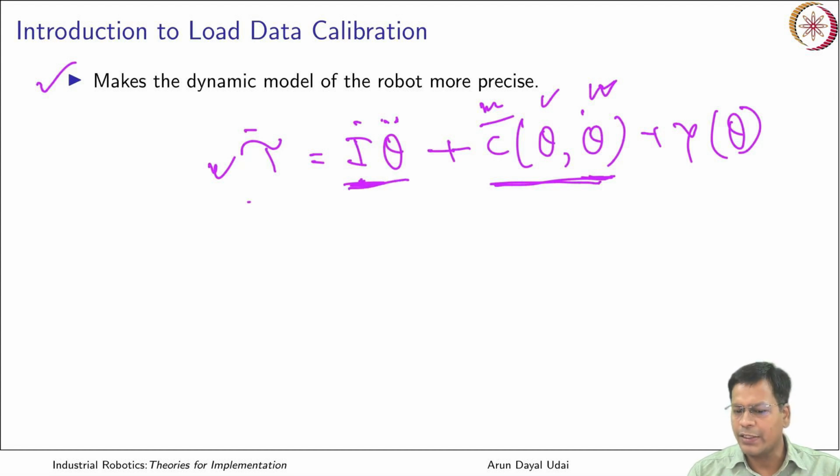Also, in case the robot is not moving, knowing the mass is very important, because of the gravity component. When you see torque, the contribution of this element is to the torque that holds the robot in its place, or just moves it at a slow velocity. So there is a good amount of contribution of moment of inertia and masses to this torque.